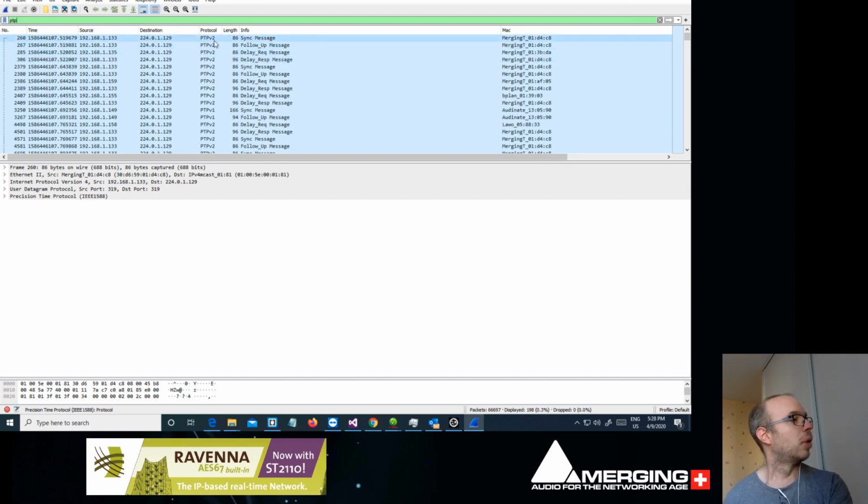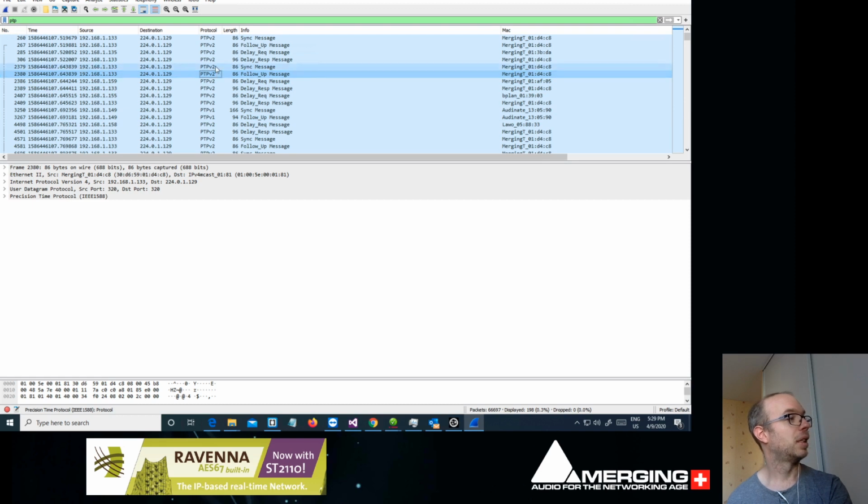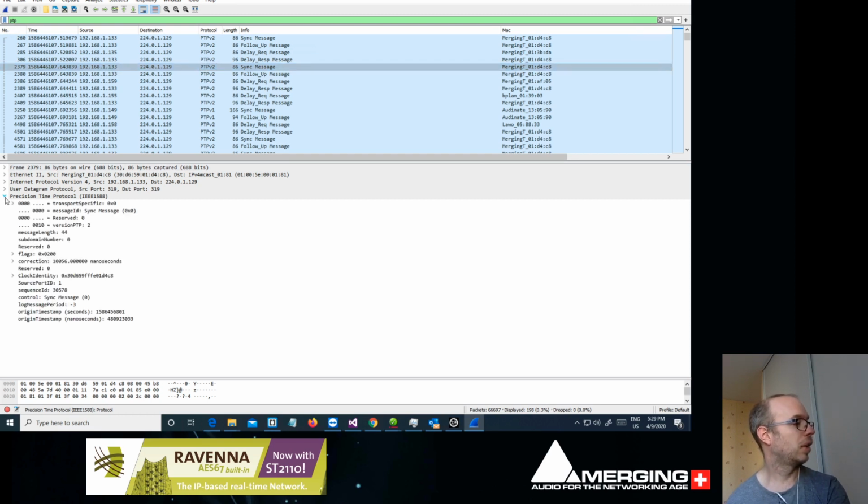We see that we have two protocols of PTP, we have the PTP v2 and PTP v1. PTP v1 is actually the Dante clock, and the PTP v2 is the AES67 clock. So we can see here that the PTP master, the one sending the sync messages, is actually the 133 device, which is a merging device.